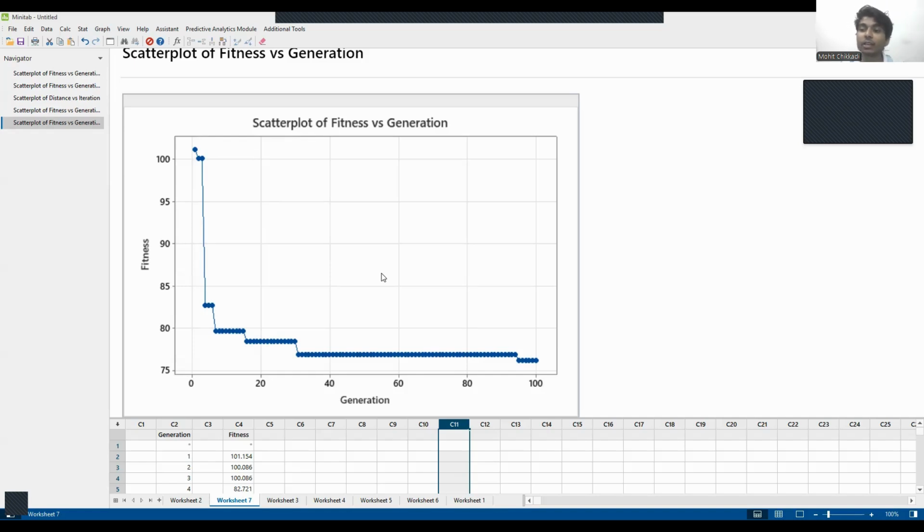As in, if the weight was distributed rear focused or front focused, the turns are not that good. If the weight is balanced, as in the chef or the food is aligned centrally with respect to your robot, then your robot takes turns much better than it would have otherwise. That is what we found with this analysis.